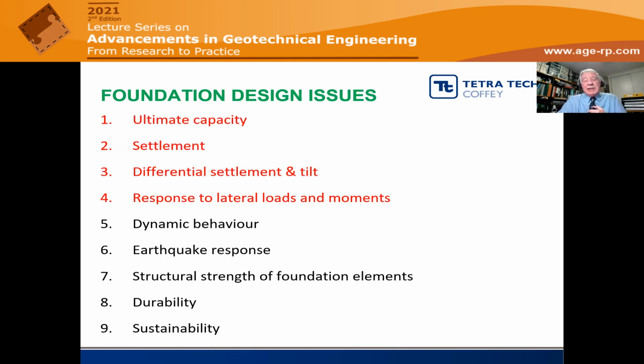And then from the viewpoint of structural design, we also need to be able to interact with our structural colleagues so that the foundation elements, the slab, the piles, if they're there, need to be designed structurally. And we also need to satisfy the requirements of durability, that in general, we need our structure to be durable over an extended period of time, typically 50 to 100 years.